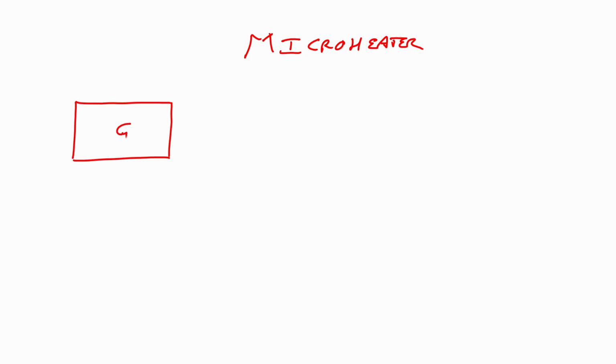Okay. So, let us take an example of a heater. So, you understand the whole process. We say micro heater because the width and the spacing between two lines are of micron dimensions. So, first step in micro heater is you have to take a substrate. Again we will use a glass to make it easier, we take a glass as a substrate. Next step is not photoresist spin coating, but we have to deposit a metal. What is the metal? We are using micro heater.